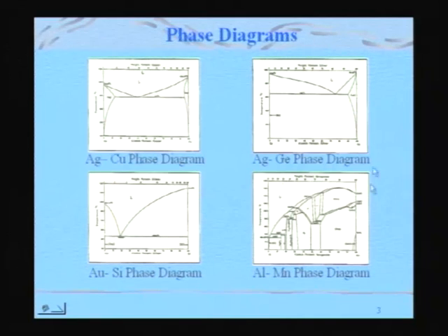So this was the kind of various metastable phases that Pol Duwez has obtained in just 1 year, starting from extension of solid solubility, then the metastable crystal structures and the metallic glasses. The only thing that had to wait for a long time is what is called the quasicrystal, for which one had to wait till 1984, and unfortunately Pol Duwez did not look at it because this is nothing but a peritectic kind of phase diagram. So he was always looking at eutectics and trying to see if